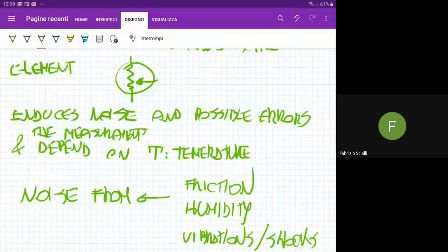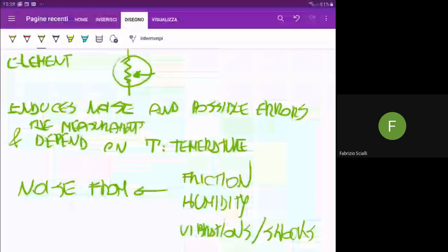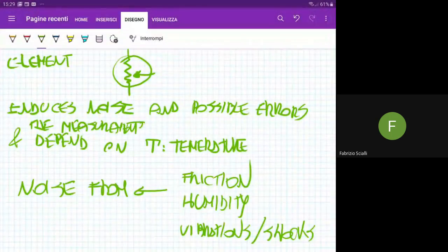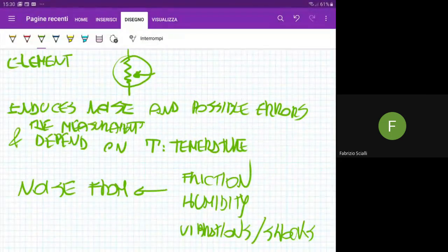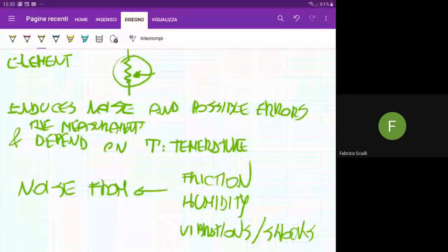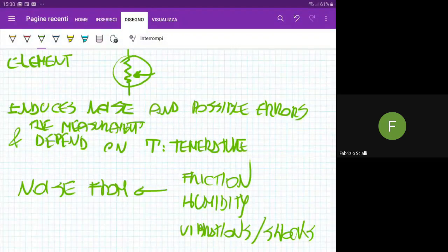The only limitation comes from the inertia of the measuring device, which could be very high, and therefore we can go up to a very high frequency of interest for our analysis, up to 500, 1000 hertz. However, environmental effects could be detrimental, like humidity, vibration, undesired shocks, temperatures, and brushing contacts that could introduce noise. These are the limiting factors.